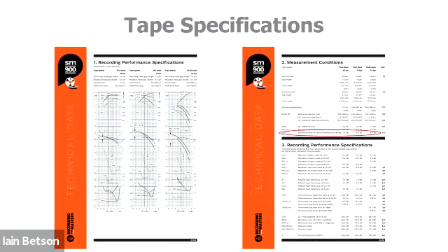It says sensitivity drop for recommended bias settings. And you've got 3 columns there, and at the top of the columns it's 30 IPS, 15 IPS, 7.5 IPS. This will tell you, and again I go into this in webinar 1 about tape lineup, how much overbias you need to give the tape when you are lining it up for record purposes.